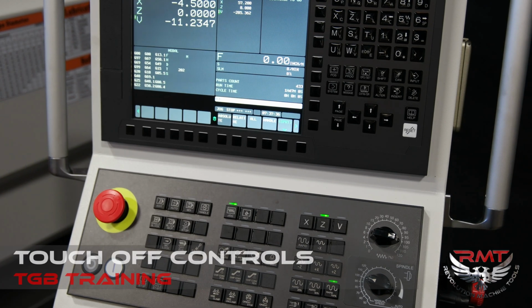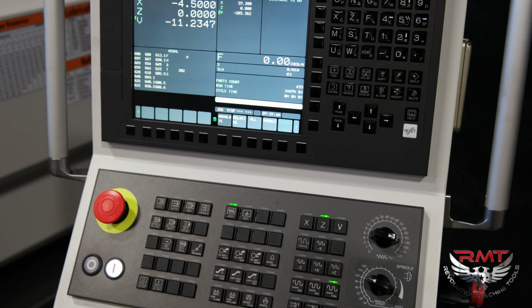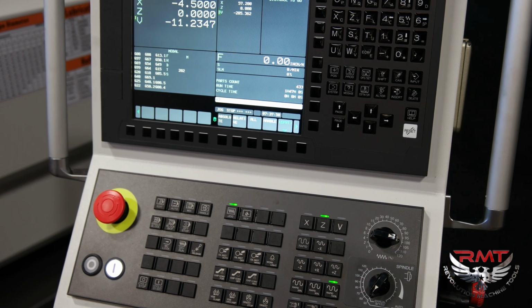Here I will show you the controller manipulation that I am using when I am physically touching off a tool. I am turning my spindle speed down to the lowest setting and turning the machine in the appropriate direction. In this case, I need to spin it clockwise to successfully work with my tools.